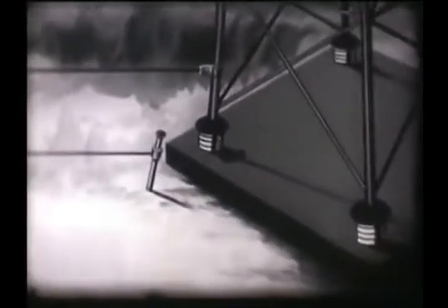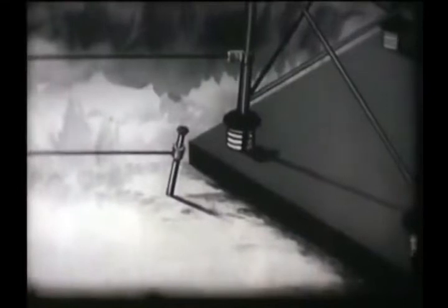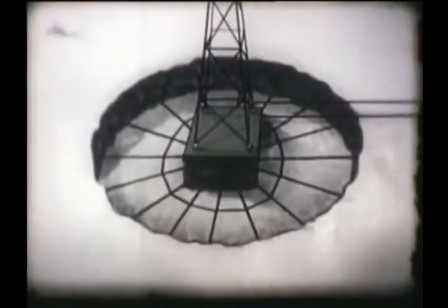The efficiency of a quarter-wave antenna depends largely on the nature of the ground. At installations near the sea or in salt marshland, the Earth's conductivity is excellent, and a simple metal stake provides proper ground. In drier regions, a system of conductors installed at the base of the tower may be required.